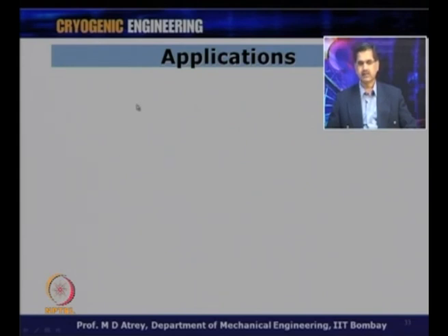We just touched upon lastly the valve mechanism, the importance of a rotary valve, the rotor and the stator, and how do they function. And ultimately, just to complete the task related to GM cooler, where do we apply, where do we find applications of GM cryocoolers? GM cryocooler has got tremendous application. In fact, GM coolers have made cryogenics very popular or to reach commercial destinations.